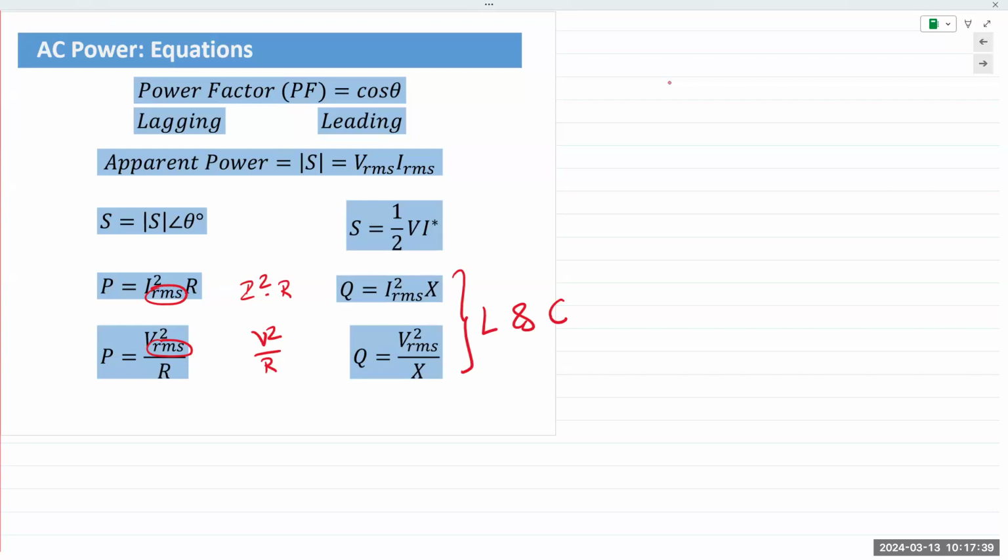If we wish to skip that step, we would simply find the voltage or the current, just one quantity. We do not have to find both. We simply take the voltage and do V squared over R, or we take the current I and do I squared times R.